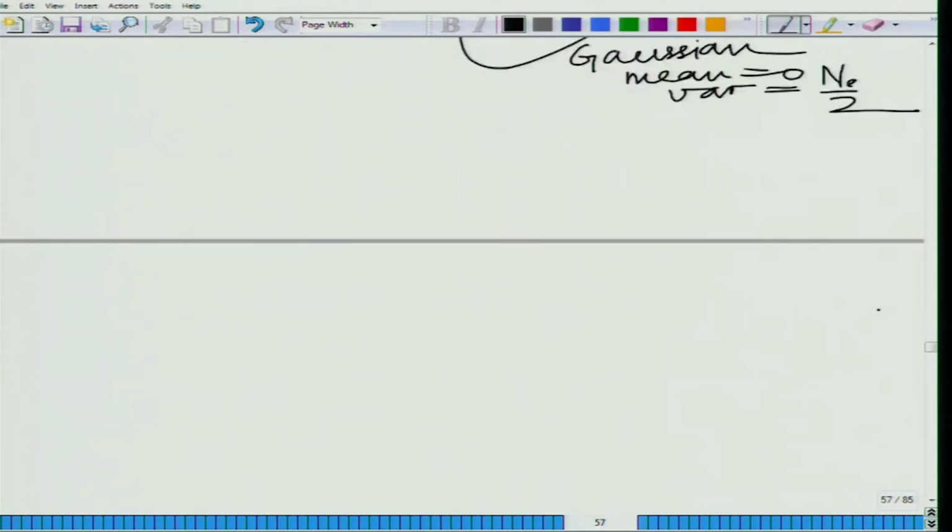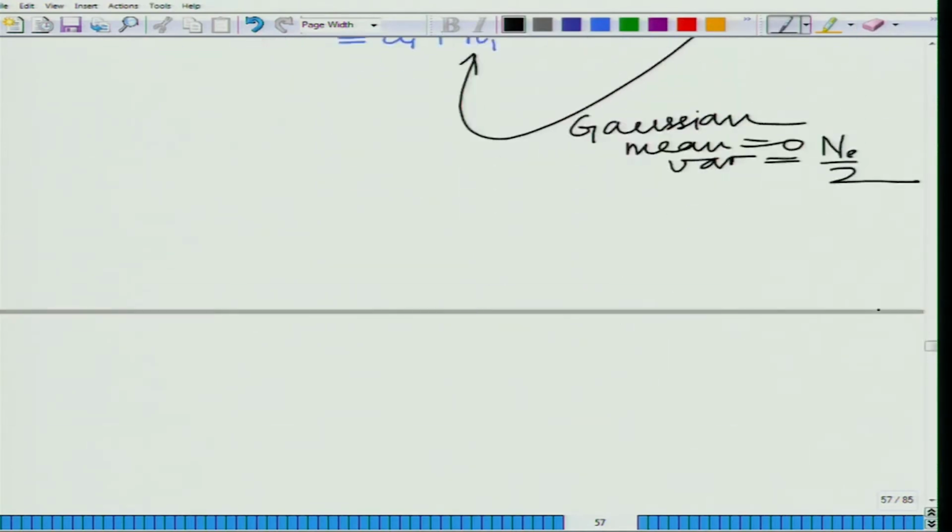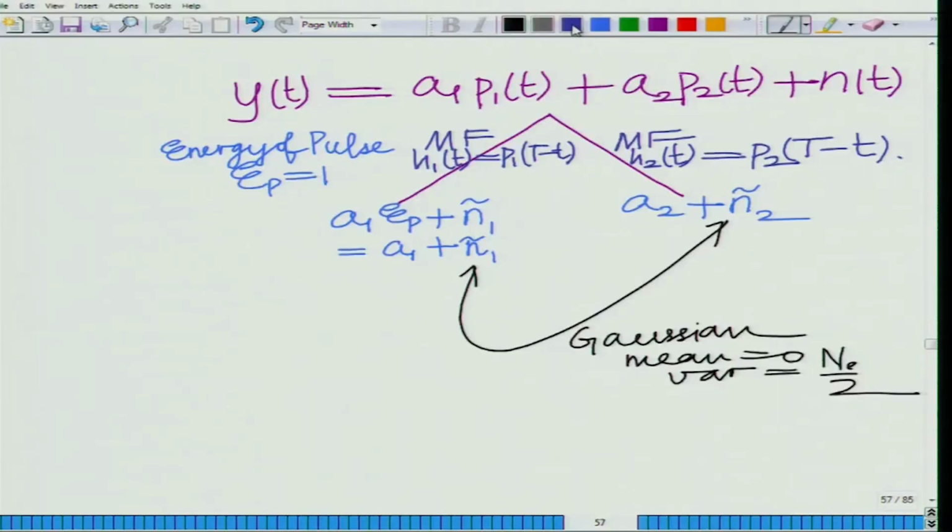And now you see there is a slight change in the detection scheme for M-ary PSK. In QPSK, for instance, and QAM, we could look at R1 and R2 separately. Remember, M-ary QAM can be thought of as comprising two constituent square root M-ary PAM constellations, correct.